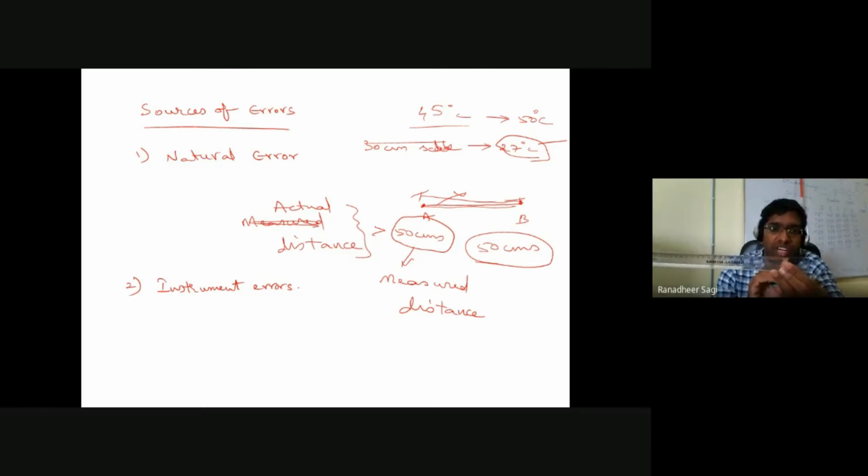Even in between 1 centimeter and 2 centimeter, I have got 10 divisions. So what does it tell me? I am going to measure my dimensions to an accuracy of 1 mm, which I am calling the least count of this particular scale. What is meant by least count? Least count is nothing but the least dimension you can measure accurately with this particular scale.